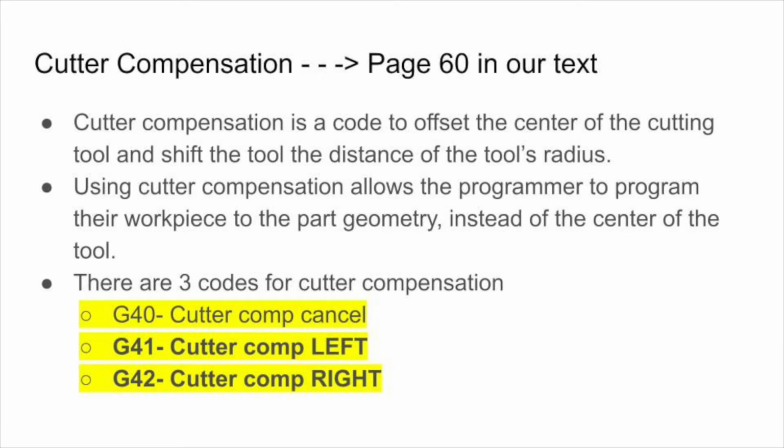G40 is cutter comp cancel. We've talked about this a little bit at the beginning of our programs. We're going to talk about how to turn it off at the end of our program. And then cutter comp left, G41, and cutter comp right, G42.